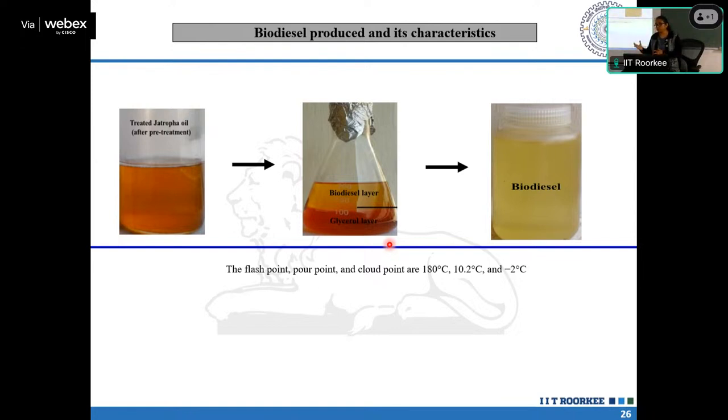We will discuss in the next topic also how to take care of that. I may reduce the diameter from 2 mm to 1 mm to 0.5 mm, but is it worthy? How much increase of efficiency or yield am I getting by spending so much energy? That is one aspect. So the other thing that needs to be done is that the viscous dissipation or the energy consumption also needs to be taken care of while you are designing. Okay, with this,